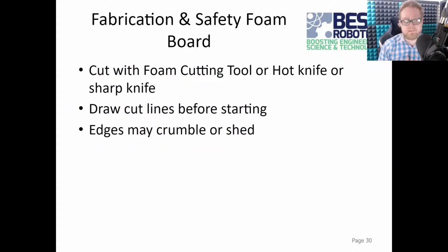The foam is notoriously hard to work with. Not because it's hard to cut, mostly because it just gives you a really rough edge. So, hot knives or hot wires are underrated in my opinion for cutting things like the foam board, but it is dangerous. So, be careful with it. Make sure you don't burn yourself. Make sure you're staying away from the hot knife. And if it's deemed too dangerous, a regular knife will work just fine to cut through the foam board. It just may give you a rough edge. So make sure that's acceptable.